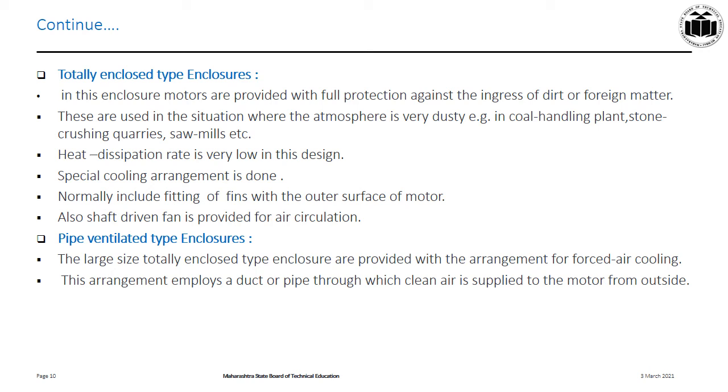It will absorb the heat energy from inside of the drive and hot air comes out of the pipe ventilated type of enclosure. So this arrangement employs a duct or a pipe through which clean air is supplied to the motor from the outside. It is a quite efficient way to cool down the drive and it will keep the inner parts safe from the heat.